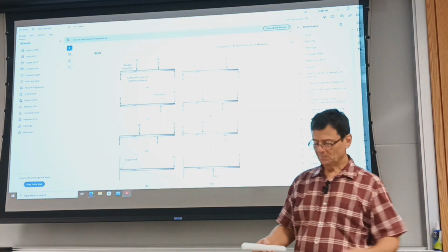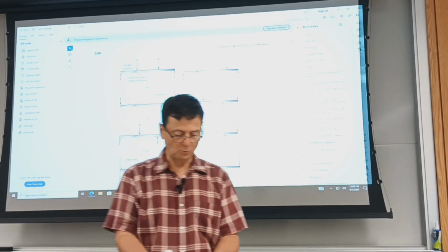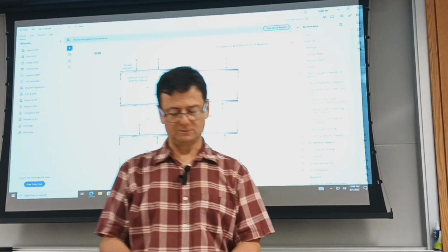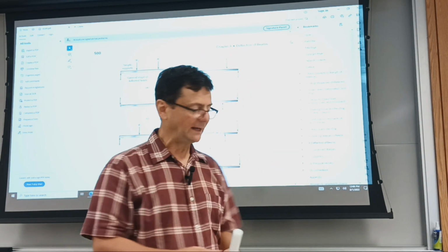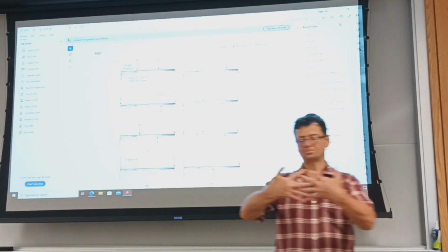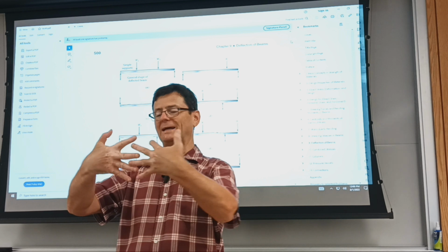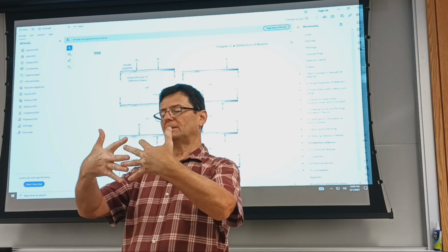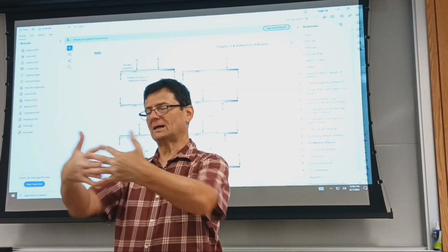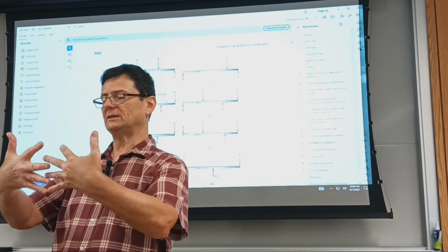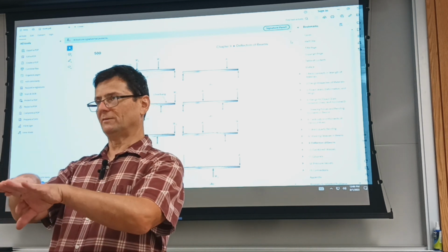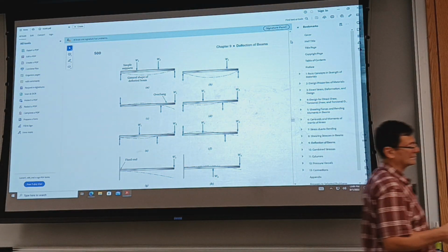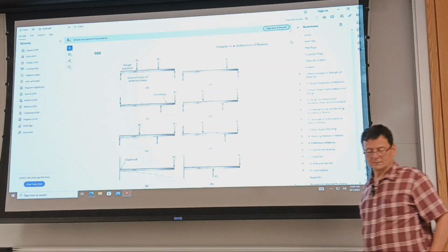You have shafts, say 2 parallel shafts with gears mounted to them, and maybe there are belts and sheaves in tension. And if the shaft deflects, again, we discussed this, if you have 2 gears meshing, and if the shafts deflect, and if they stay parallel to their planes, the gear is not as bad, but you can also have rotation, and the gears, instead of meshing nicely on the width of their teeth, they start meshing on a side, and that's increased contact stress and accelerated wear, and you don't want that to happen.